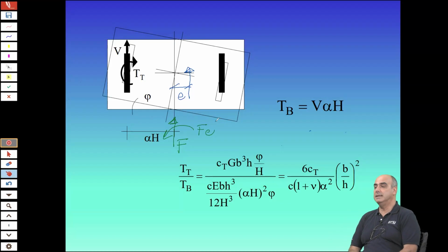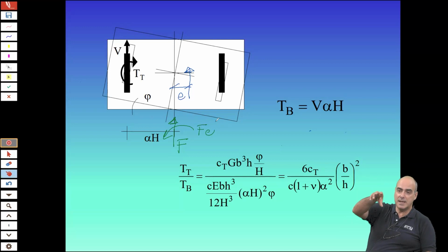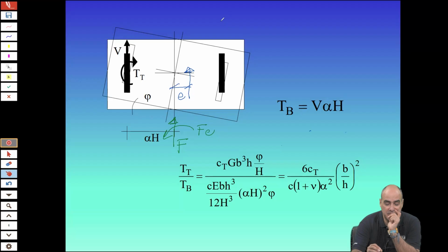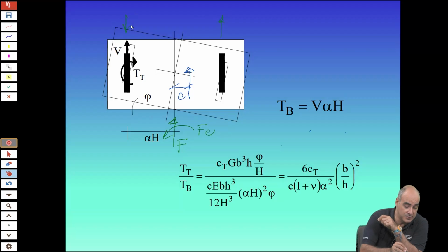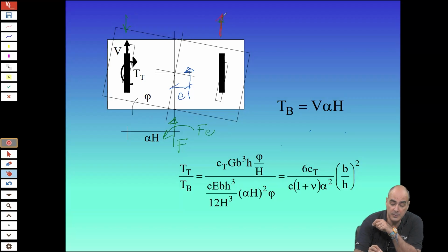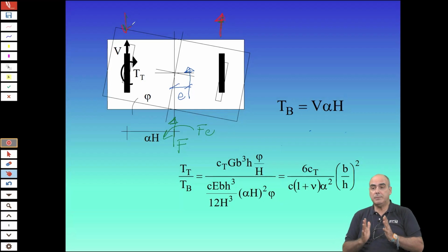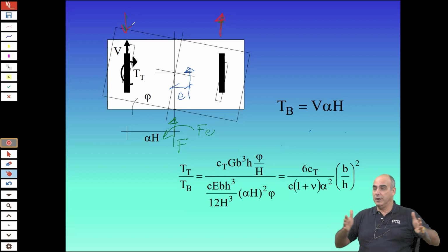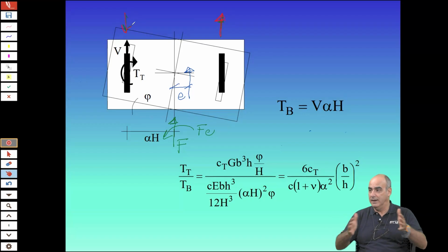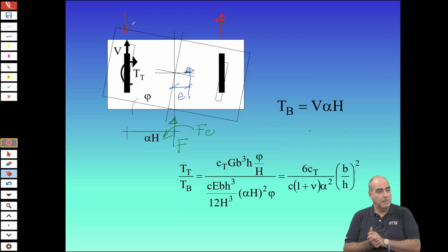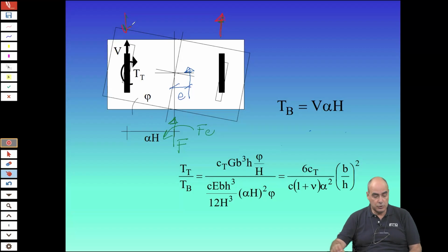And in a system like this, how do you resist torsion? It's not very clear. Let's try to see another column. You resist torsion in this way. You exploit the fact that you can have parallel shear walls, but they are not concentrated. They have a distance between them. You exploit this distance to provide the wall system a torsion resistant capacity.